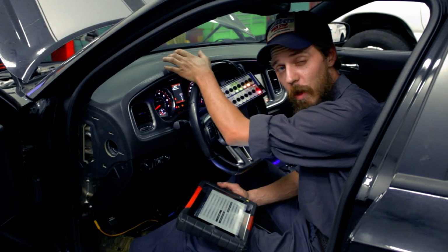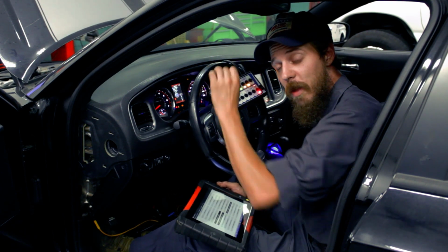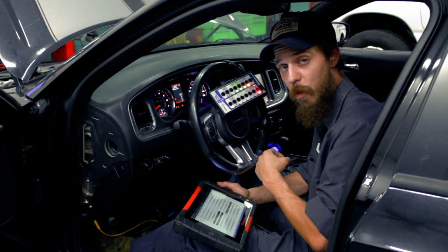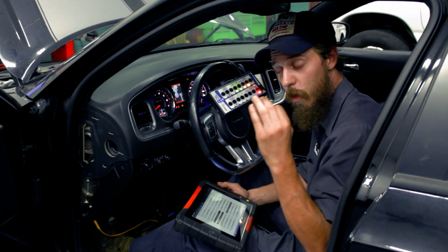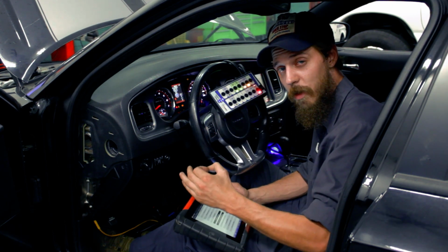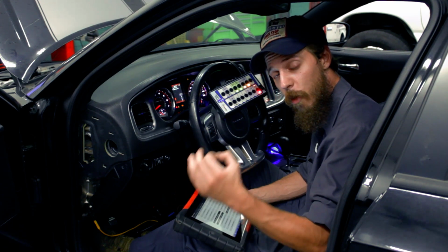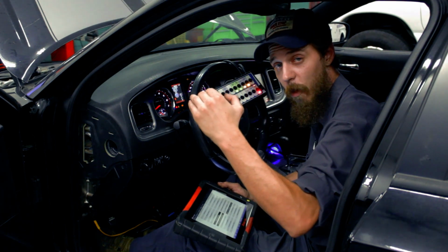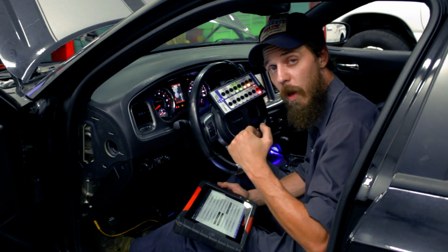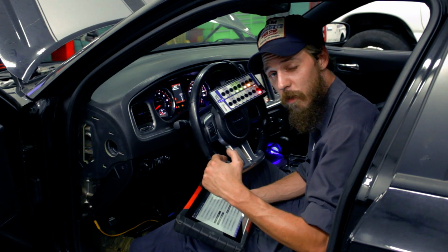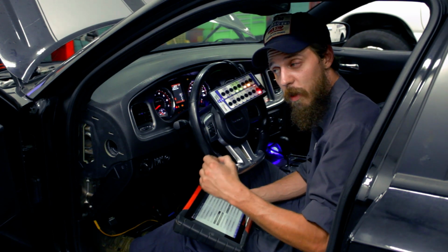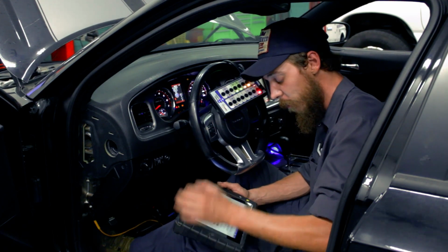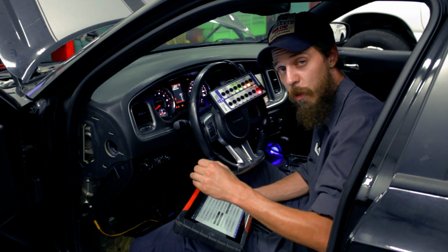It is read directly by the powertrain control module and then sent over the CAN bus network to our transmission control module. That goes from an indirect to a direct input once we go into reverse or drive, based off the design of the switch. We go from that high system voltage, battery voltage, down to a negative temperature coefficient temperature sensor. I believe, I may correct myself right at the bottom of the video here, and then it reads actual transmission temperature.